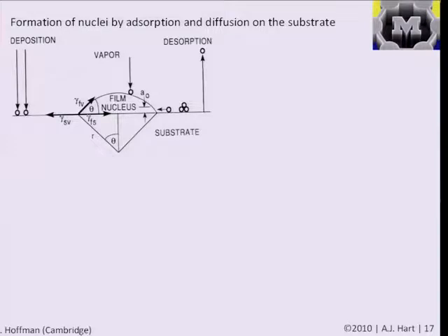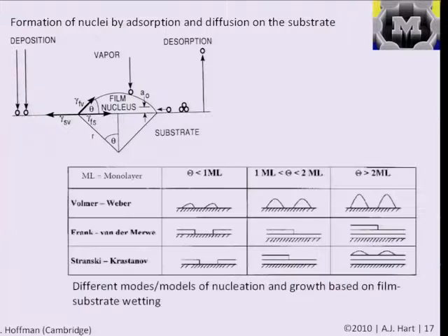And the kinetics of these individual processes of adsorption and sticking and diffusion and desorption determine the kinetics, the nucleation and growth process of materials on substrates, and are essentially the initial stages of growing a film, which are in many ways the ways that you grow nanostructures on a surface.